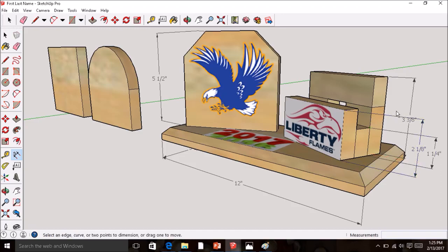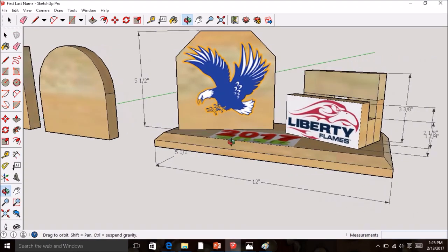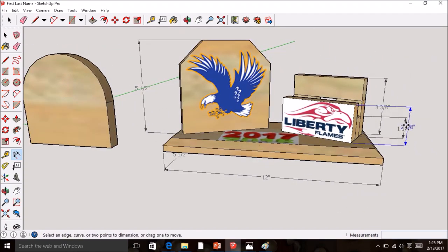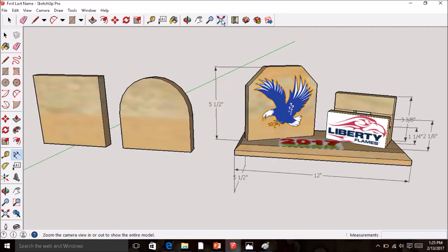But so I should have my dimensions on the side, my dimensions on the top front, and we can kind of orbit around, and if you need to move any of these, you can come in and move them a bit so that they're legible. And if this one's not quite showing up, you can move it down. But you're gonna go ahead and you're gonna dimension the whole thing. Hit zoom extents, make sure they're still showing pretty good. You're then gonna go ahead and click leader. Click on this point. You're gonna come in and you're gonna type